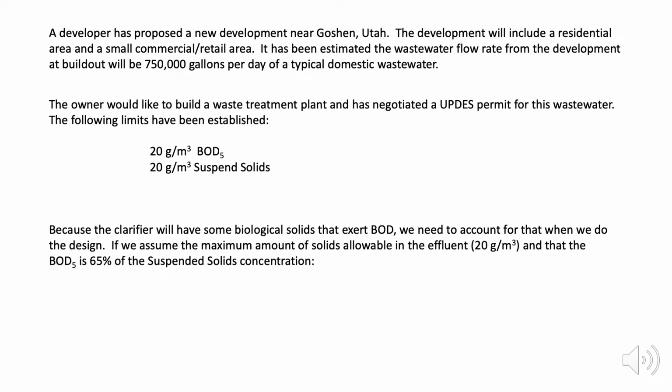Because the clarifier at these treatment plants doesn't work perfectly, in fact, some biological solids are going to escape from that clarifier, and when those solids escape, they're also going to exert some BOD. So we need to account for that when we design the treatment plant.